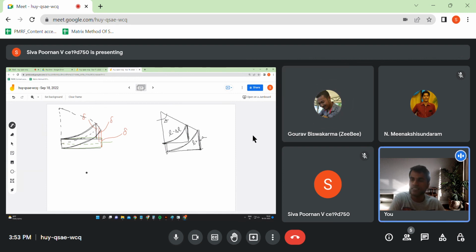What I think is that if we have a complex geometry, we use a particular interpolation function to assume the boundary itself. Another thing is that we assume how the displacements vary between two nodes. So these two interpolation functions are different. If both of these displacement functions are taken to be of the same order or identical, then I believe that element is called the isoparametric element. But anyway, I'll go back to it again and try to give it with more examples so that it will be clear to understand.